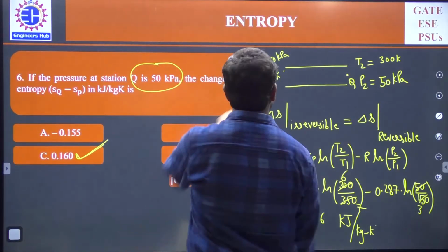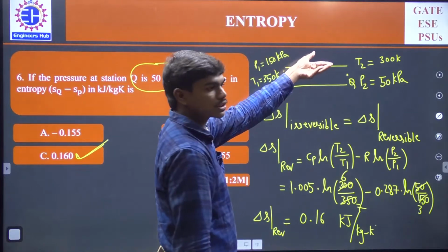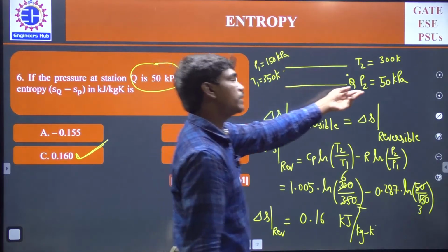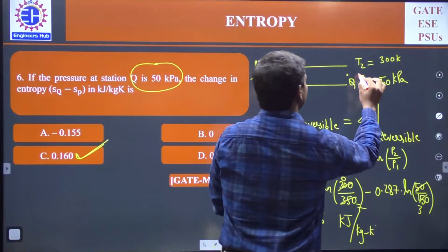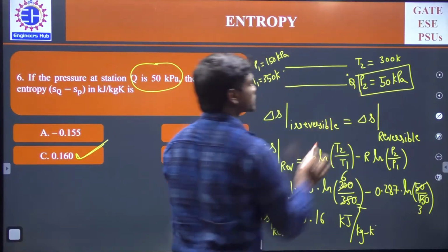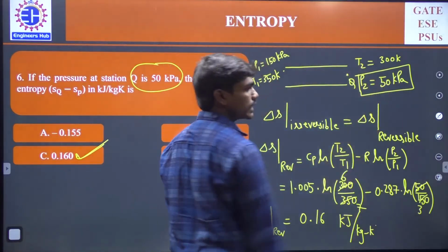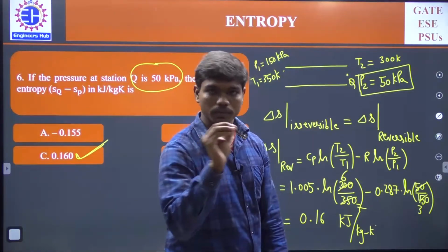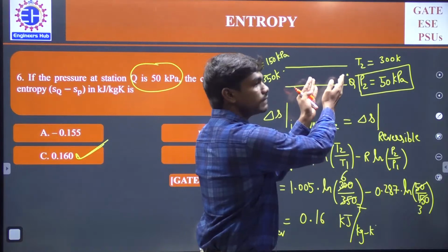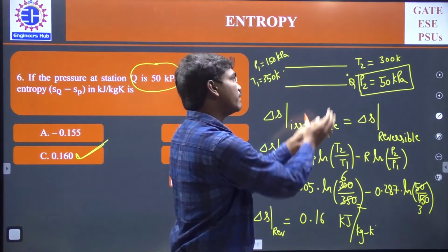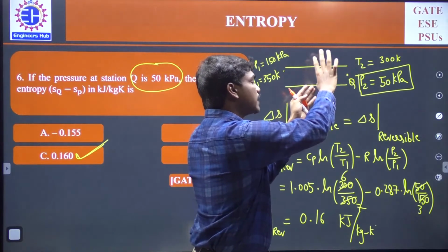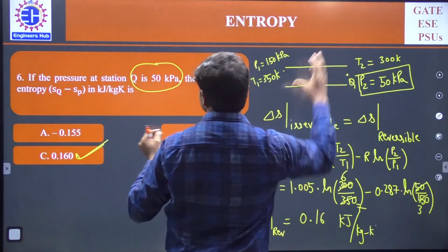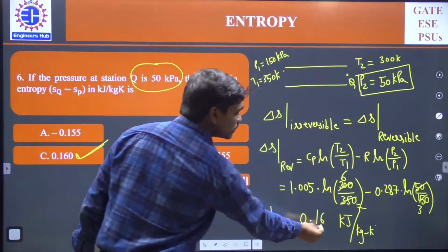Even though there is no heat loss outside the system, the maximum possible pressure is 87 kilopascals but only 50 kilopascals is the exit pressure, which means some pressure energy of the fluid got lost because of irreversibilities. This is an irreversible process, which means even though you don't have any heat interactions, your entropy is increasing by a small amount.